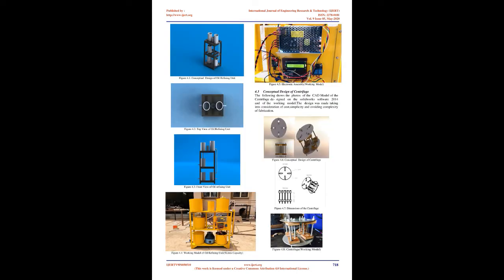Sedimentation/decantation. During this stage, the oil was allowed to sediment in the beaker for 4 hours and was decanted into another beaker, while the residue at the bottom of the beaker was discarded. Filtration. The sedimented oil was finally filtered using a filter cloth and the filtrate was collected in a filtration flask and was observed to be clear, while the residue, the filter cake, was discarded.